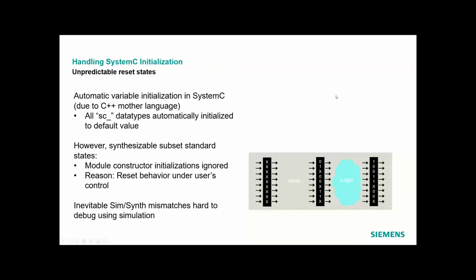So this is what can go wrong, and SystemC has no concept of X state because that's undefined by the standard, but OneSpin has support for X value checking. So it is definitely worthwhile to check what is uninitialized and what can cause potential X on the output side.